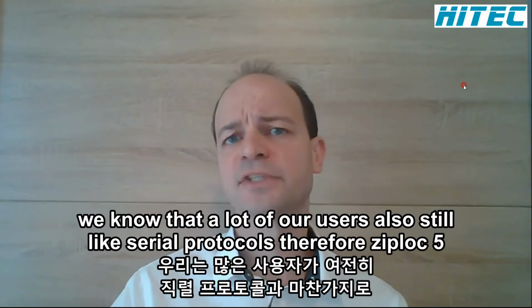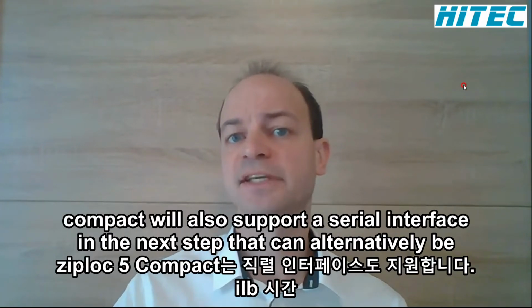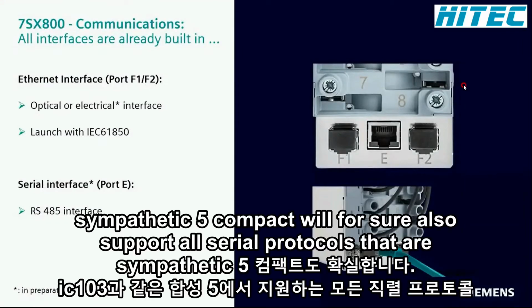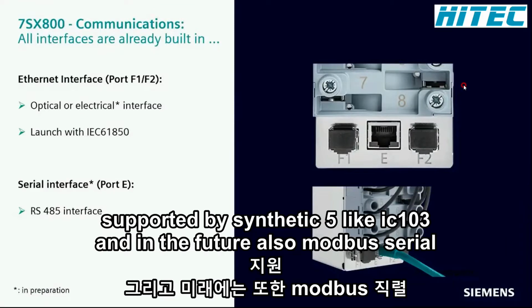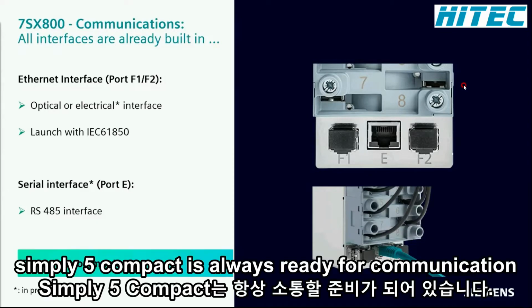We know that a lot of our users also still like serial protocols. Therefore, SIPROTEC 5 Compact will also support a serial interface in the next step that can alternatively be used for IRIG-B time synchronization. The serial interface port E is located right in the middle. SIPROTEC 5 Compact will for sure also support all serial protocols that are supported by SIPROTEC 5, like IEC 103 and in the future also Modbus serial. SIPROTEC 5 Compact is always ready for communication.